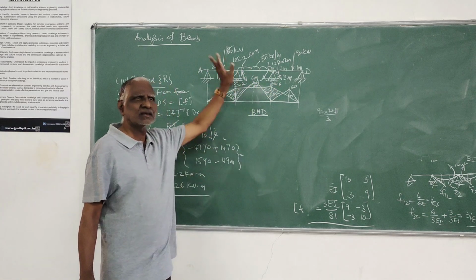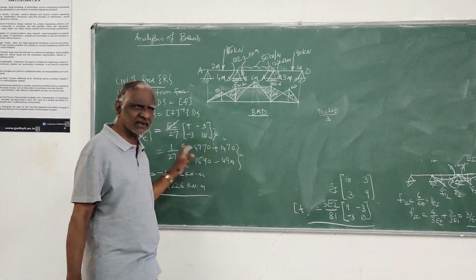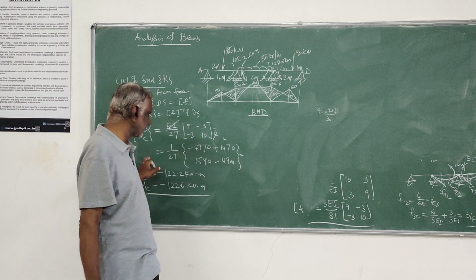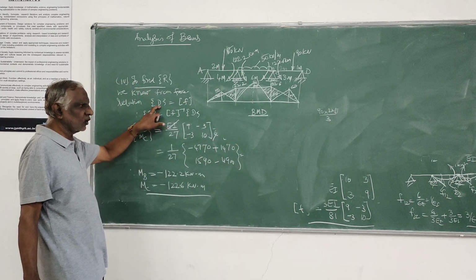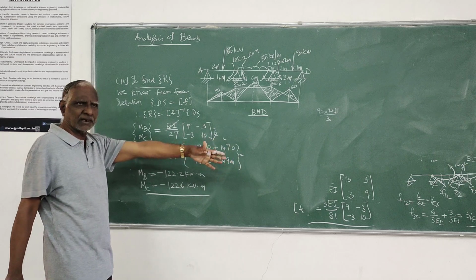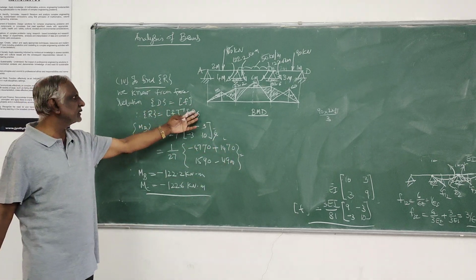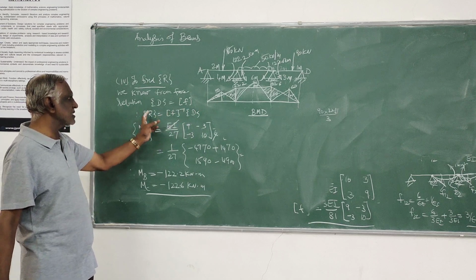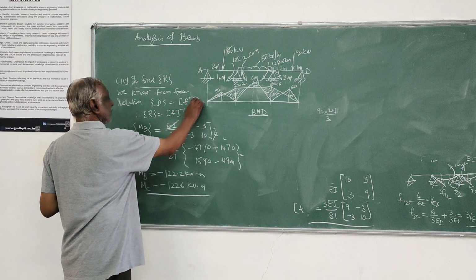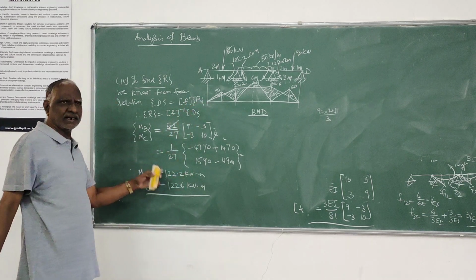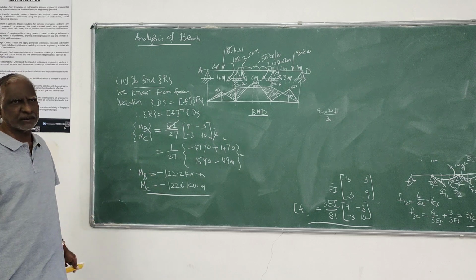You have to select the vertical reaction. Otherwise, you can follow this as the general step. And once you calculate that D, that is the displacement on account of the load, generate the flexibility matrix by the usual procedure, then use the simple force displacement relationship, D equals FR, and work out the redundant. Once the moment redundant is evaluated, you can plot the bending moment diagram.